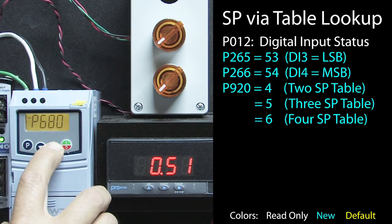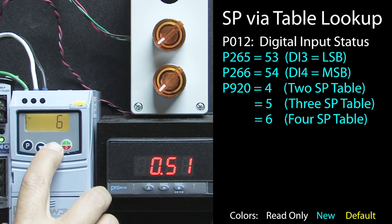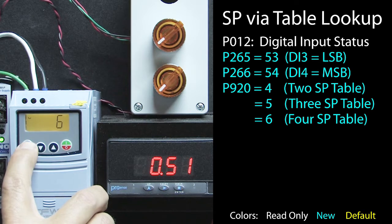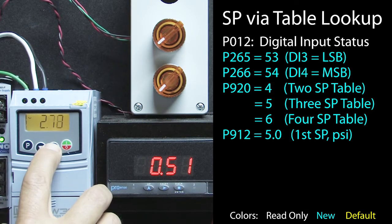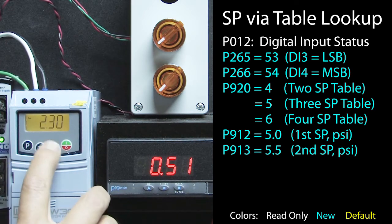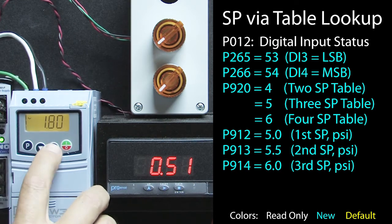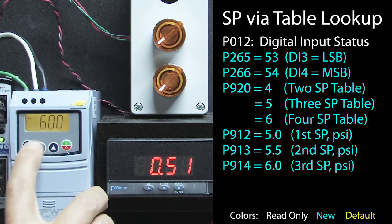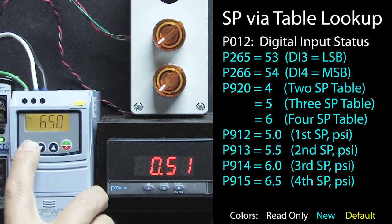And let's go back to parameter 920 to tell the PID application to use digital inputs 3 and 4 to select the set point values from a table. Now we'll go to parameter 912 to enter the first set point. How about we make that 5 psi? Parameter 913 is the second value. We'll make that 5.5 psi. Parameter 914 is the third value, so we'll make that our usual 6 psi. And parameter 915 is the fourth value, so we'll set that to 6.5 psi.